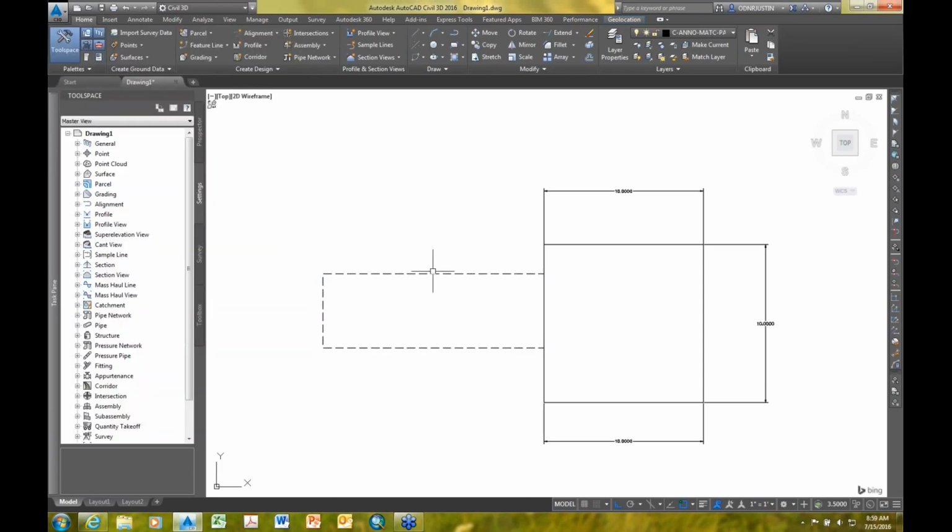Close that down. Now you didn't see anything change there. You did with the line type, but not with the line weight. If I go down and click on my display line weights button here, it'll show the print version of the line weight. That could be cluttering to your drawing and you want to leave that off while you're doing your work, or maybe you want to see how it's really going to look on paper and turn it on. So that's where that button is located.